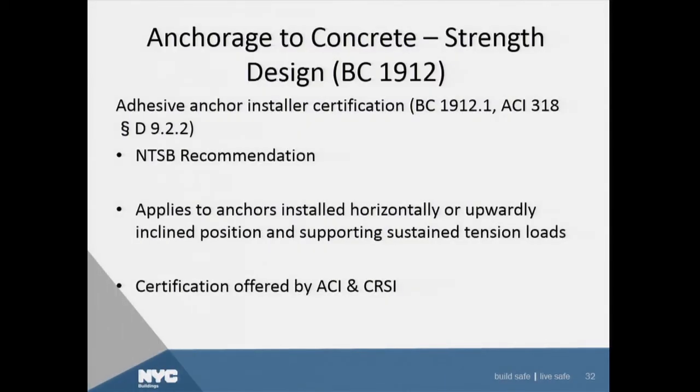Okay. Anchorage to concrete design based on ACI 318 Appendix D. One of the changes here is the installation of adhesive anchors in certain instances, basically from the horizontal position to the inclined vertical to completely vertical, has to be done by certified concrete installers. The ACI provides a certified installer program nationwide, and they go through this on a regular basis. The courses are available, but this is going to be required going forward as part of the 2014 code.